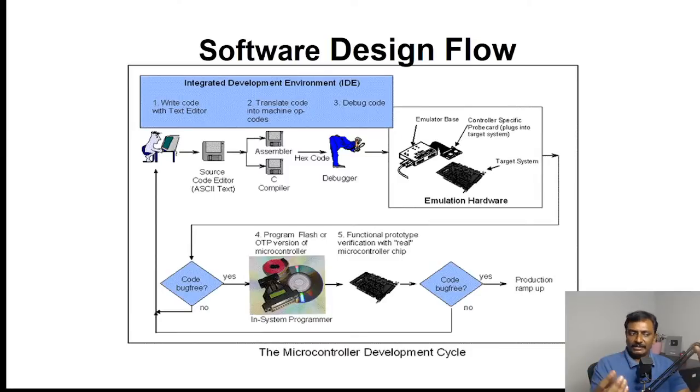So you have to choose the IDE and write the code on that. It's embedded C language, and mostly the code will be similar to C language. Finally, you'll get the hex file. Only the hex file will be downloaded inside these microcontrollers.